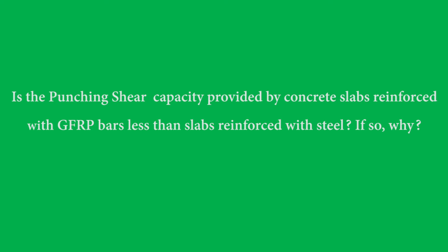So the intact part of the concrete in these reinforcement conditions is almost 1/4 to 1/5 of the steel in GFRP. So having this in mind, we have a smaller shear-carrying intact concrete after the section is cracked for GFRP. For that reason, this formula of punching shear is reduced by the coefficient of 5k divided by 2.